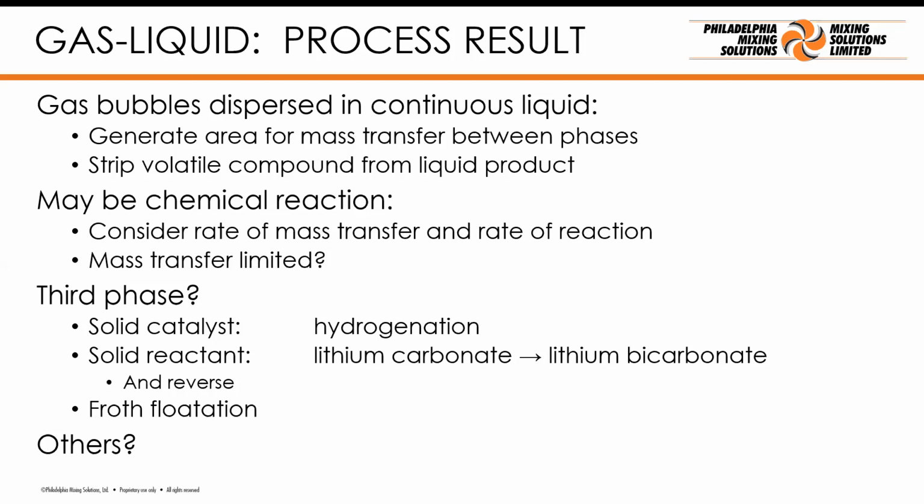I work in flotation. It's very important for me to keep the suspension of the particles in a flotation cell, and at the same time, you use the impeller to disperse the air. So essentially, there are two objectives there. One is to get smaller bubbles, and at the same time, you want to keep the particles in suspension.